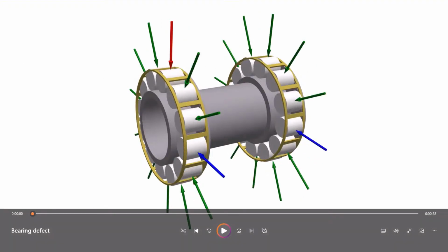By looking at this animation, we see the roller forces, and such bearing simulations, I will say, are invaluable, allowing us to predict and plan for the forces within our bearings, and to understand how clearance, defects, and system dynamics contribute to the overall bearing load profile.